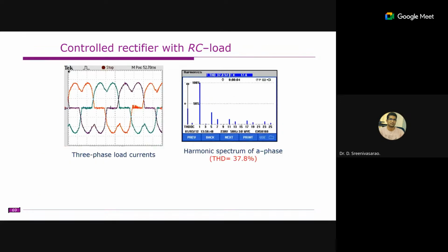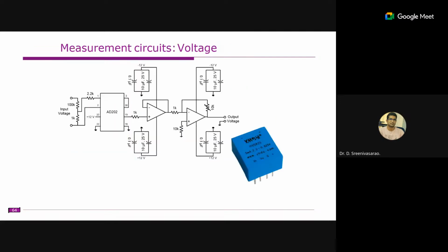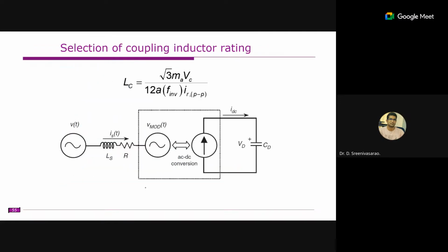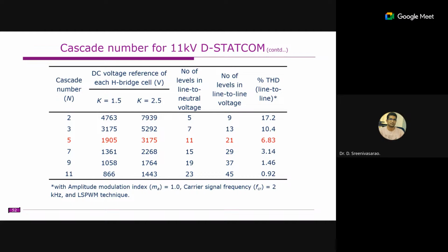You can actually design this something like this. You can use the H bridges, like 2 H bridges. So this will be the DC link voltage. But if you are using 11 H bridges, this will be each cell voltage, and this will be the minimum voltage, maximum voltage. You can impose some design principles on this, right?